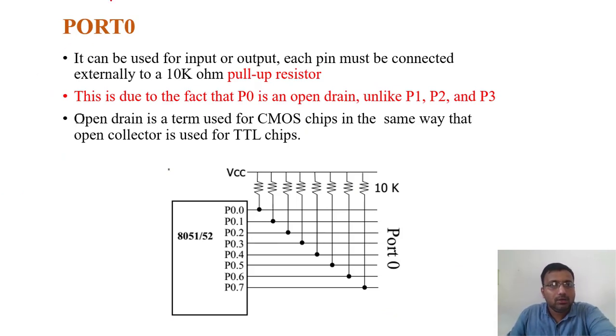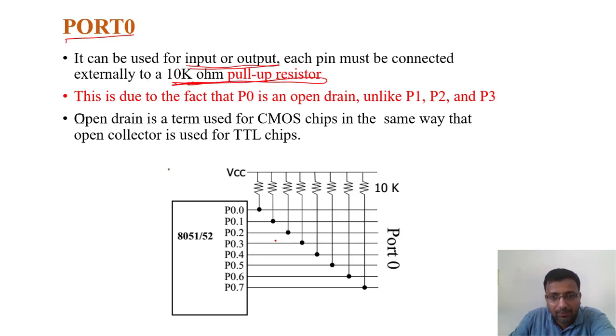Okay, next we'll see in detail a study of port 0. Port 0 can be used for input and output, so we can use it for both activities. Each pin must be connected externally with a 10k ohm resistor, that is, a pull-up resistor is required.